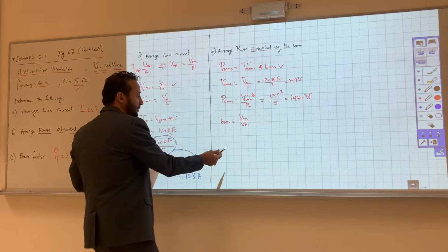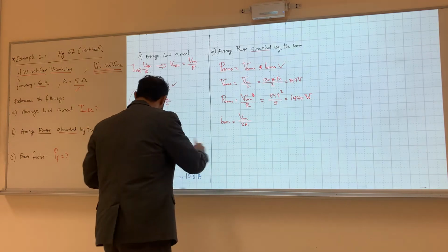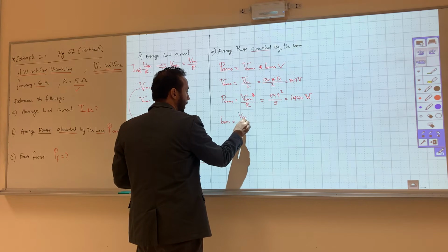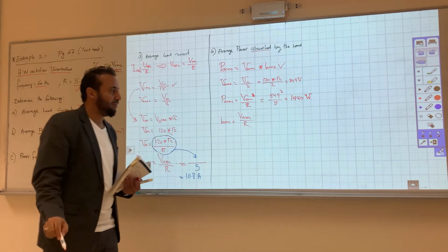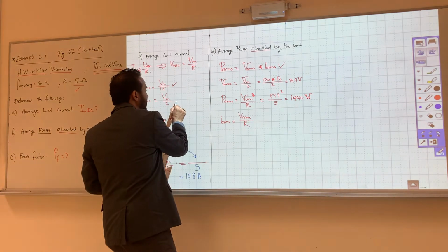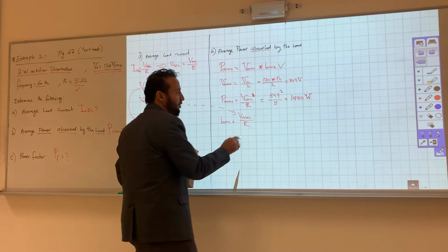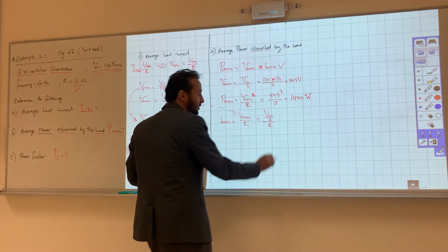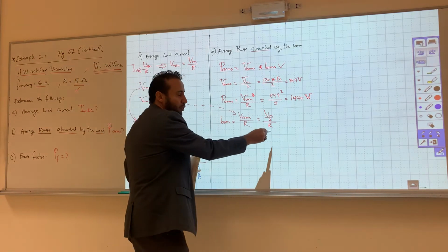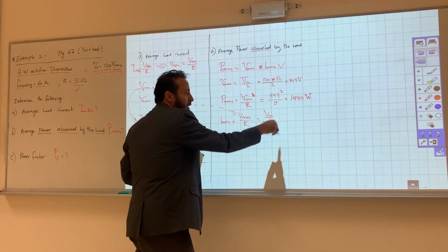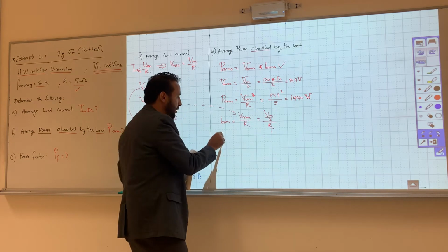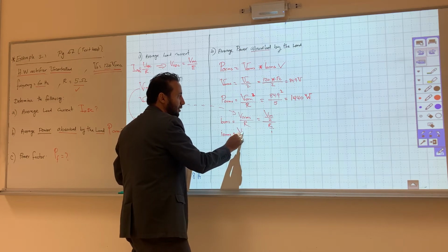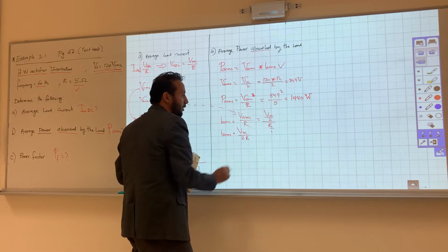So we know that by Ohm's law, if I derive this, I out RMS equals V out RMS divided by resistance. So if I take this here and insert it right here, it will be Vmax over 2 over resistance. So you know what you need to do. You flip, you put this one over 1, and you convert it to multiplication, and you flip. So I out RMS equals Vmax divided by 2R. That's how we get that equation.